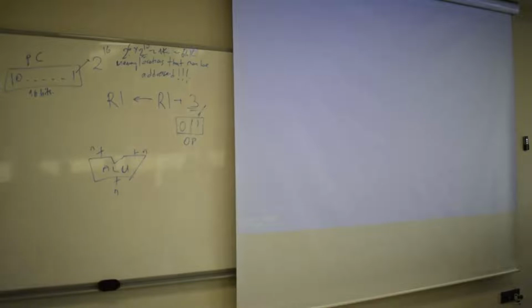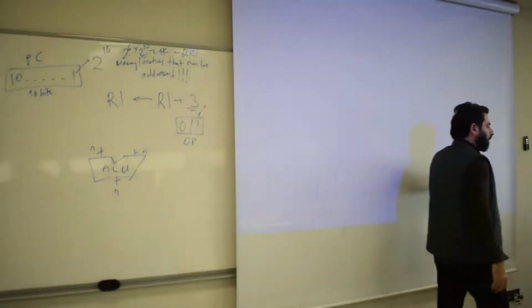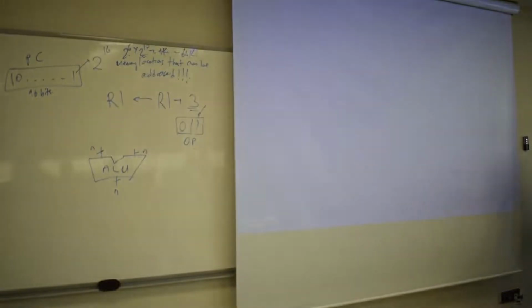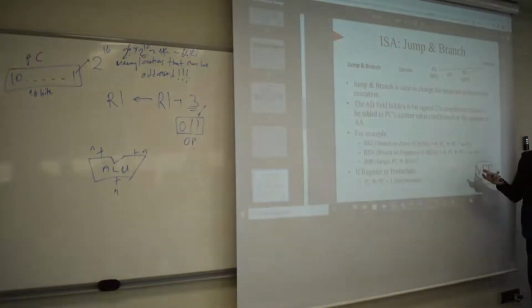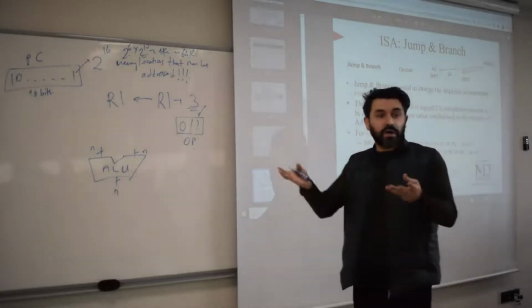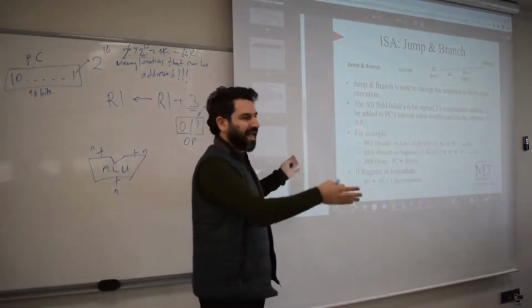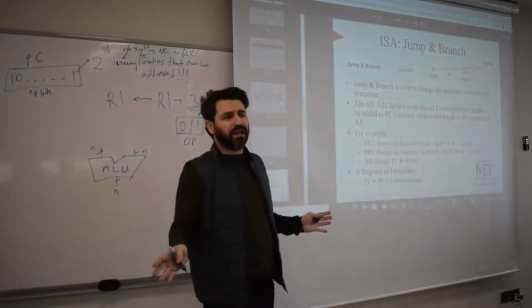So this is the problem of the design. The program counter should be selected to contain more bits, not just 16 bits. Okay? So you see, we actually caught a problem in the design. But that's okay, because this is a toy example. You would never use it in practical circumstances. This format, or this ISA, instruction set architecture, is not something real.